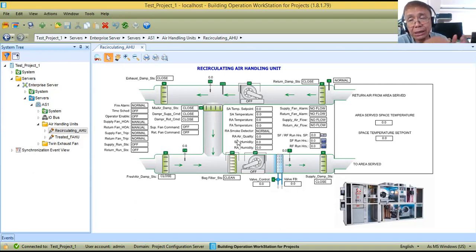Okay, because as a BMS engineer, you should always be protecting your DDC or your controller. So as much as possible, you can accommodate 24 volts in your DO points, but if 240 is the control voltage of the motor control, you have to use separate relays.